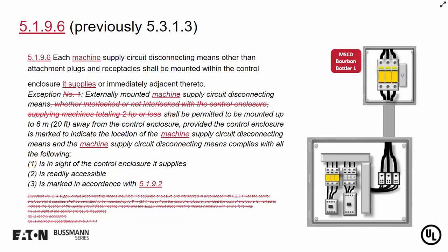And I'm getting a lot of questions about how NFPA 79 is enforced. NFPA 79 is really a customer-driven specification requirement for the construction of the equipment. And as you can see, there are a lot more stringent requirements for that, both electrically as well as the safeguards of the machine, which we're not going to get into today. We're primarily focused on the electrical.